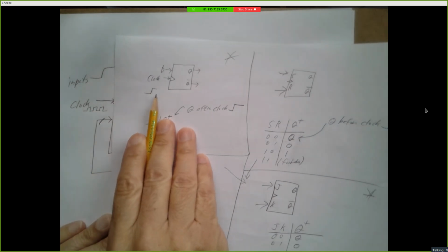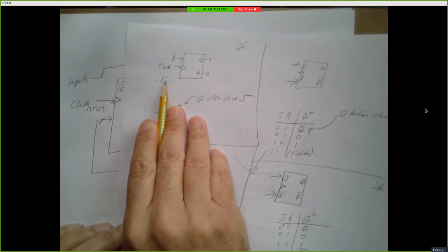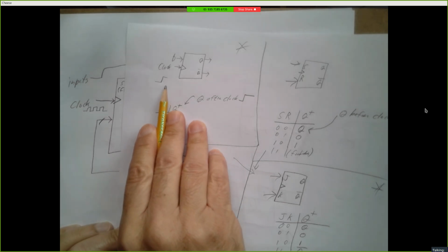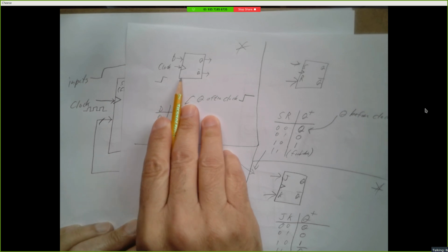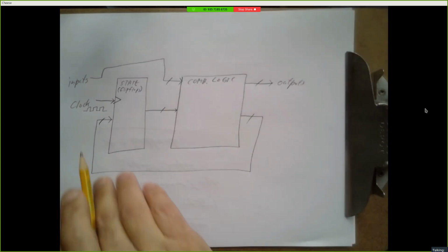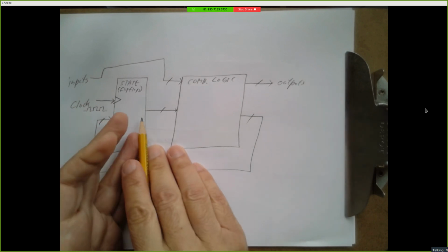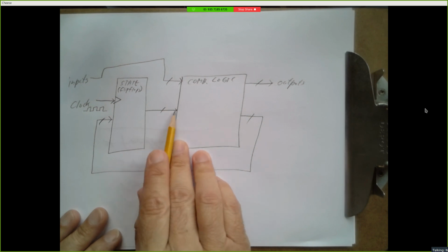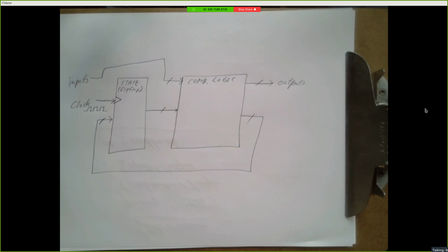And then, some eons later, a fraction of a nanosecond, eons to a transistor, the clock drops, and still nothing changes. But then eventually the clock will tick upward again, and when that happens, all of the inputs that you've set up here now modify the outputs. And once those modify, this line of values changes, the inputs to the combinational logic change, and the whole thing happens again.